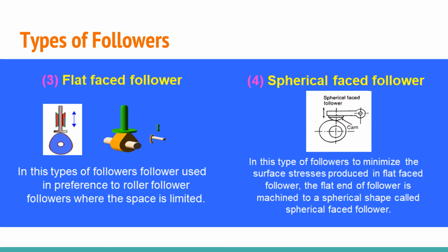The next is spherical face follower. In this type of follower, to minimize the surface stresses generated between the cam and follower, the flat follower is machined to a spherical shape. Then it is called a spherical faced follower.